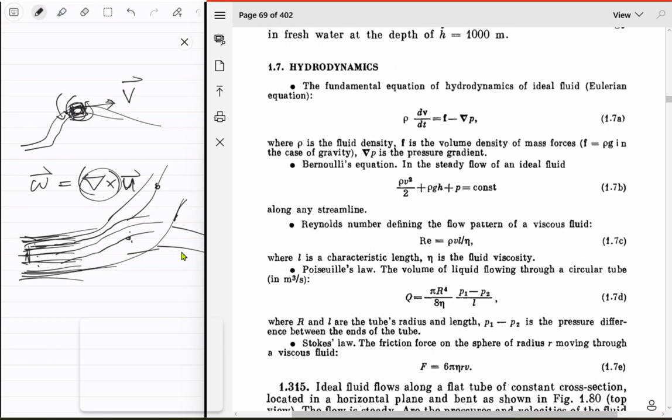Oh, and by the way, when I said there will be a difference in the pressures, there will be the opposite difference in our rho gh terms themselves, right? So actually that would mean that these constants are in fact the same already. We don't have to think of a very thin tube. You can already apply Bernoulli's equation in every single case. Oh, yeah, I didn't think about it till now.